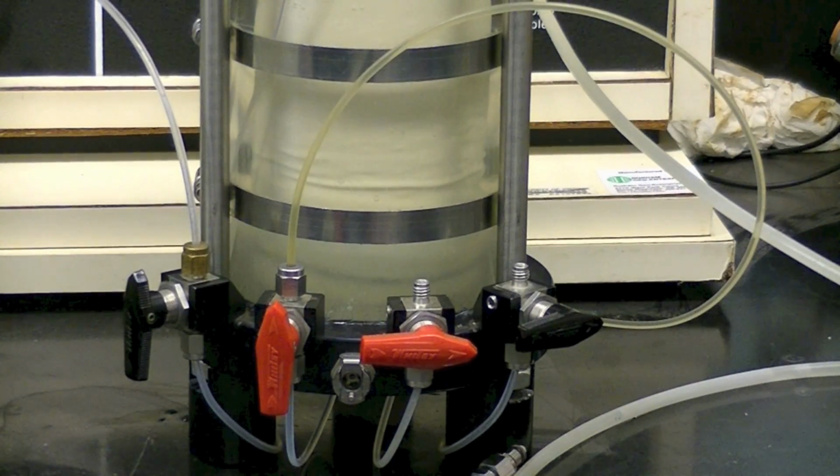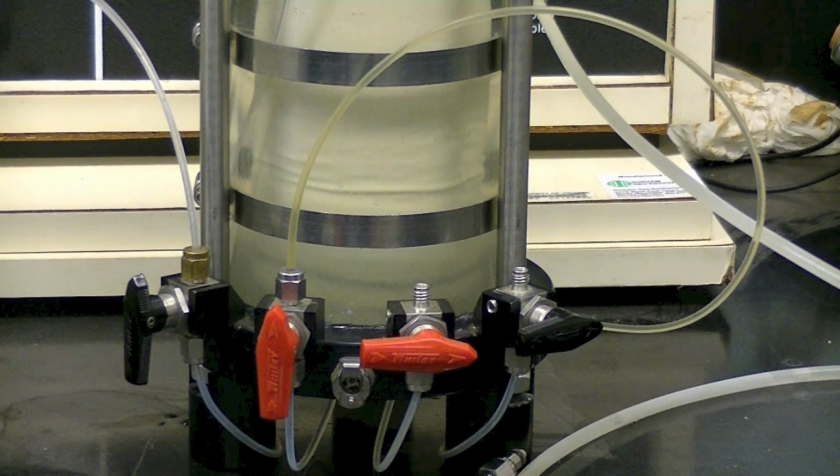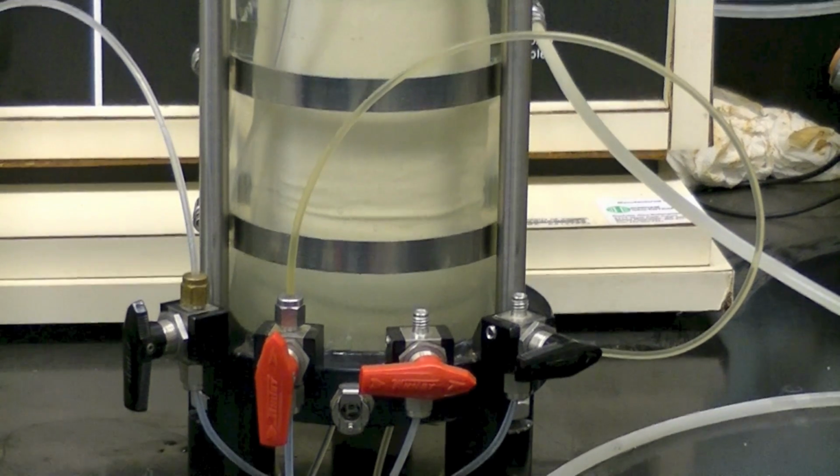Connect a drain line from the board to the red nozzle inlet so that the regulator controls the red or bottom inlet. Similarly, connect a drain line from the board to the black inlet so that the regulator controls the black or top inlet. In our case, regulator 1 represents the top and regulator 2 represents the bottom.